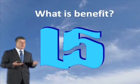Now, if the building control say to you, I'm not happy, I'm not giving you 15% where it is, what I'd say to them is, where would you like us to see this smoke detection then? Where do you want it? In other words, I want to get the 15% extension with travel distances, where would you like us to put this? It's a bit of an L5 system, a bit of an engineered solution. That's when you get the benefit. Ultimately, building controller, approved inspector will agree or not agree whether or not 15% is a benefit.